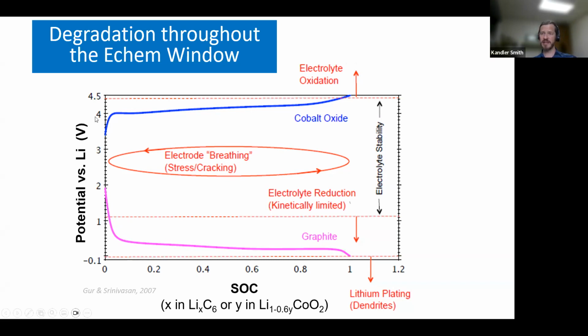But if you could safely implant a lithium reference electrode inside a commercial cell, it would be a big help towards isolating those mechanisms. But typically we're always doing something invasive whenever we're messing with a really big commercial cell from a vendor. If it's a pouch cell, you can slice it open and maybe get a lithium reference between some layers or on the side. But it's troublesome. You're always doing something invasive. So that would be really useful.